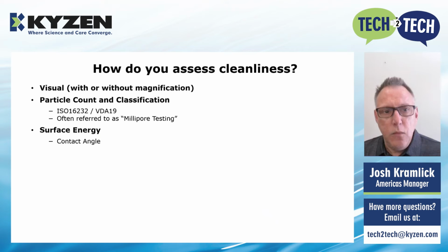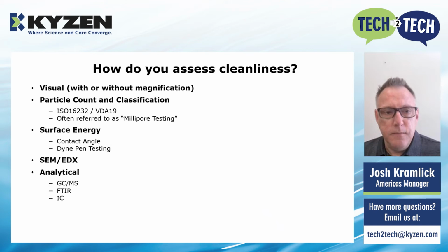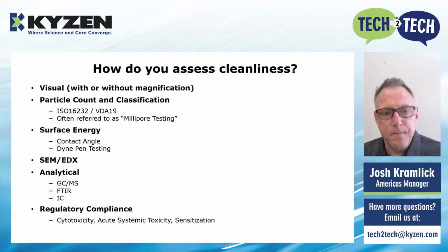Surface energy, whether you're measuring contact angle or using dyne pen testing to assess the residual organics on a part. Perhaps SEM EDX, where we're looking at elemental or compositional analysis. Other analytical methods, including gas chromatography, mass spectrometry, Fourier transform infrared spectrometry, ion chromatography, and in some cases, we have regulatory compliance concerns, such as cytotoxicity.